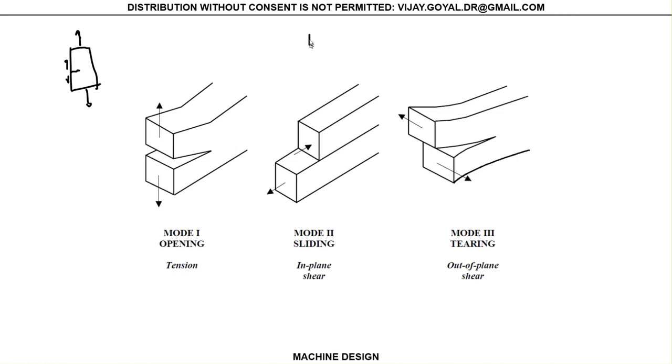You can have the case of a joint, where you've got a bolt and a screw, and you're pulling on one side and pulling the other side the opposite way. This is called a mode 2 type of crack. This is rarely seen, but you do have these cases, especially with twisting. If I was twisting a structure, then this mode failure will show up.